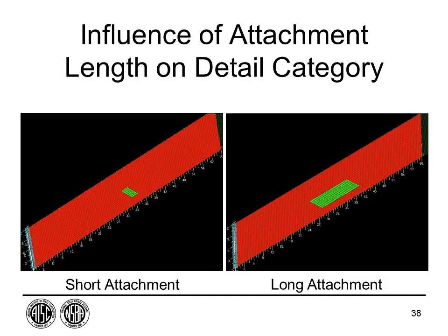Other things related to stress that are difficult to quantify, especially years ago, is attachment length effects. We'll talk about that. If you can think of stress like water, that's a very good thing. This is a simple little finite element model of a plate subjected to tension in the direction I'm moving my arrow, with a little attachment sticking out perpendicular to it. Same exact plate, same exact load, but now I've just made the attachment longer. And if you think about it, I can get a little bit of stress into this plate. It's not fully effective, but the longer I make the plate, well, then it becomes more able to carry stress. That's a shear lag effect.